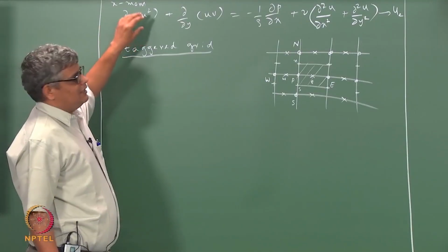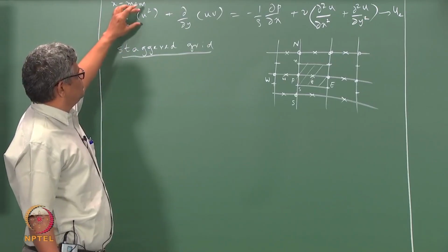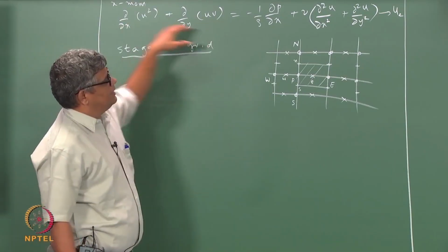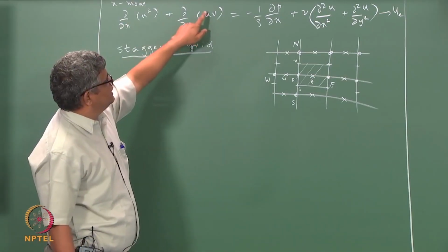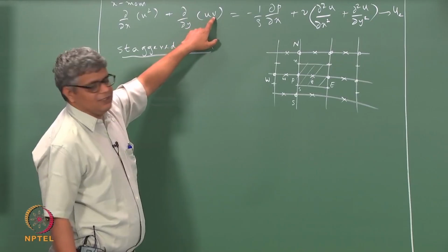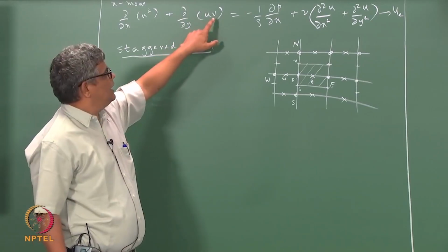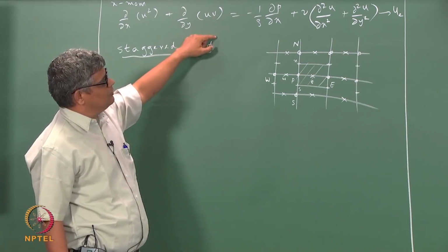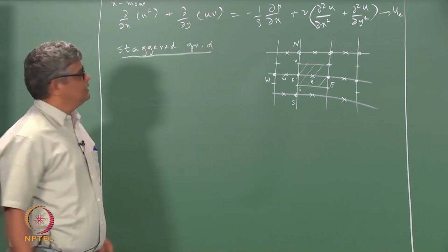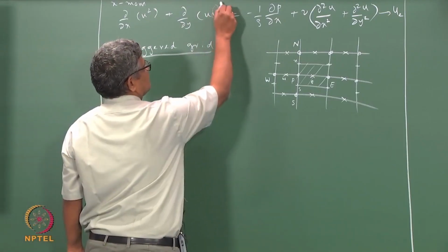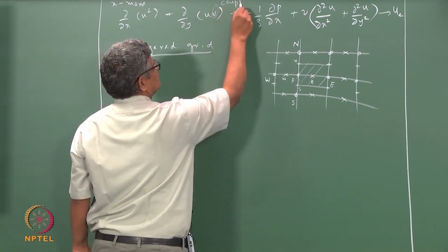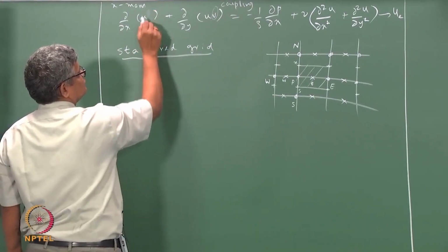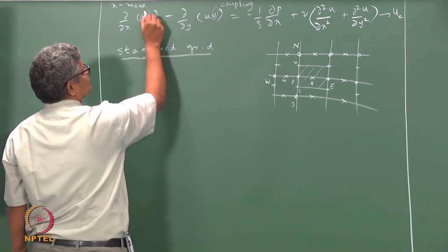Normally we have a constant times u, and here in solving this we are trying to get u, and v is supposed to be a coefficient, and we do not know the value of this coefficient v. It comes from the solution of the y momentum equation. So this constitutes coupling, and this, which we can write as u times u, constitutes nonlinearity.